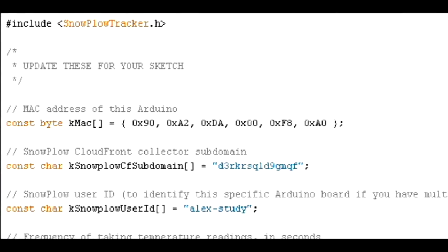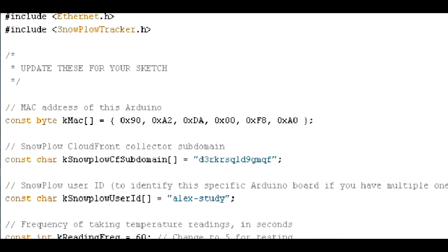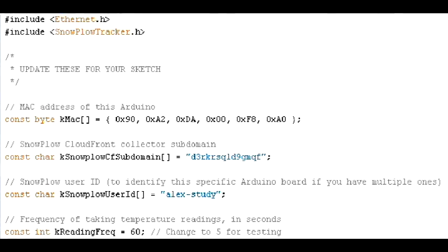A function is a named piece of code that can be used elsewhere in a sketch. There are ways of calling functions that have already been defined in the code, either in your sketch or as a part of the Arduino language. These parameters can be used by the pinMode function to decide which pin and mode to set. The pinMode function configures a pin as either an input or an output. When configured as an input, a pin can detect the state of a sensor like a push button, but as an output, it can drive an actuator like an LED. There are several other functions in the sketch section, but I only discussed a few.